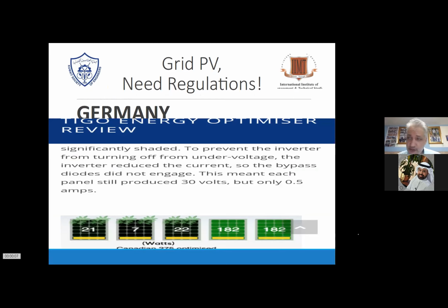By law in Europe, or in Germany especially, with the VDE and similar inspection and commissioning criteria, if it's higher than 30 milliamps, you would need a second earthing at the chassis.